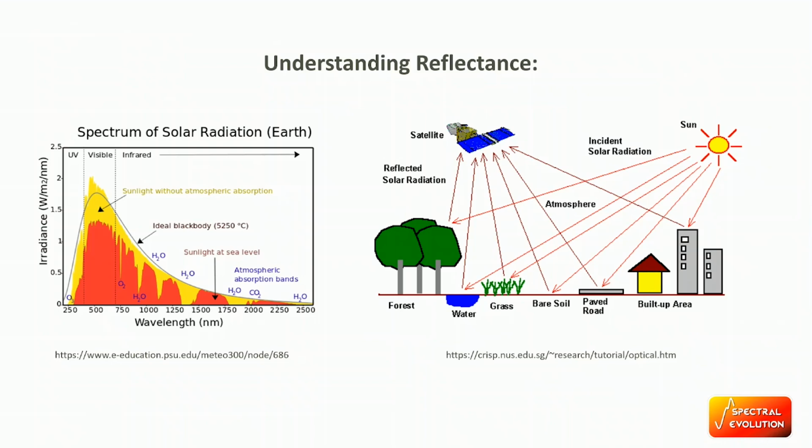So here on the left is the solar radiation curve, and on the right are different materials that will absorb differently, which should all have different reflectance curves. And something else that should be noted is the two water absorption features in that left curve at 1400 and 1800. Those are water bands. You can see that there's no signal there. That's why when you're taking outdoor measurements, you'd see noise in those areas because the atmosphere is absorbing most of the radiation there.